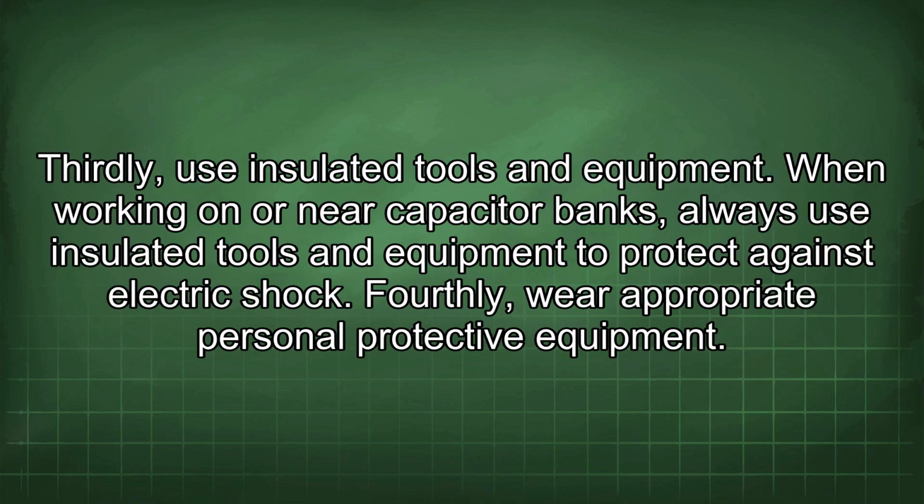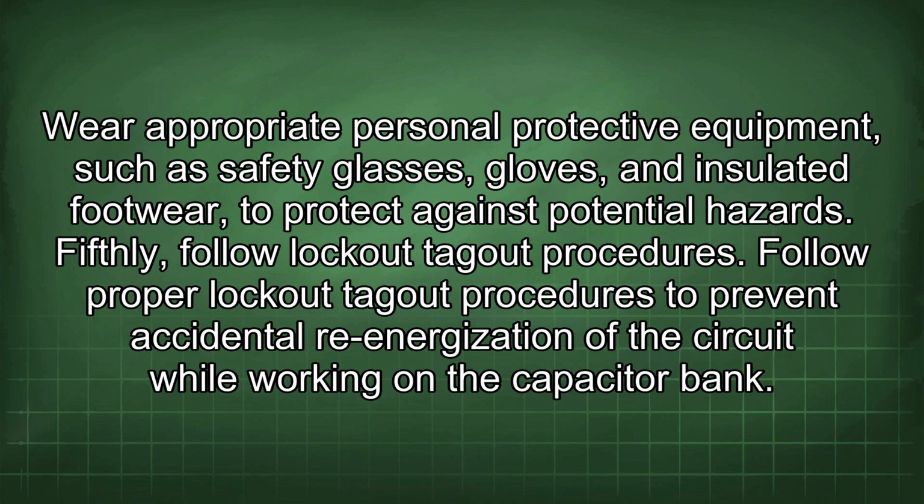Thirdly, use insulated tools and equipment. When working on or near capacitor banks, always use insulated tools and equipment to protect against electric shock. Fourthly, wear appropriate personal protective equipment. Wear appropriate personal protective equipment such as safety glasses, gloves, and insulated footwear to protect against potential hazards.